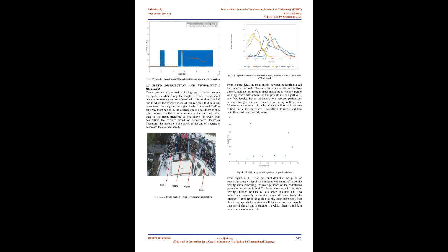Between the selected time frames, all the moving pedestrians corresponding to that time frame will be chosen. One needs to define the desired direction for pedestrians so that they can easily move from origin to destination. In our case, the length of the road stretch is around 50 m. So we divided the length of the road into segments, and at the end of the divided segments the desired direction is given. Now, we selected the 10 surrounding pedestrians, which will change all over the length, from which the interaction force between pedestrians is calculated.